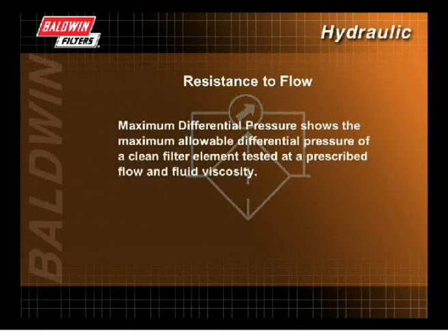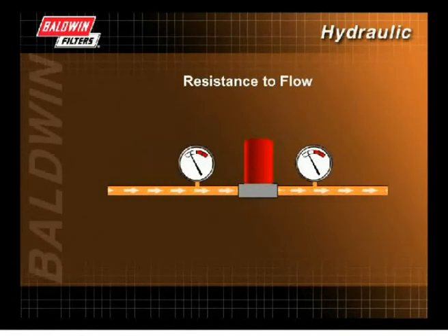Resistance to flow, or maximum differential pressure, shows the maximum allowable differential pressure of a clean filter element tested at a prescribed flow and fluid viscosity. The resistance to flow through the filter is very important. This resistance, or pressure drop, has direct bearing on the filter life.